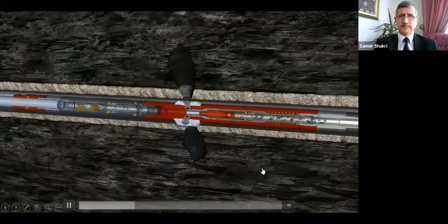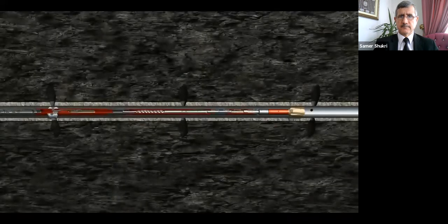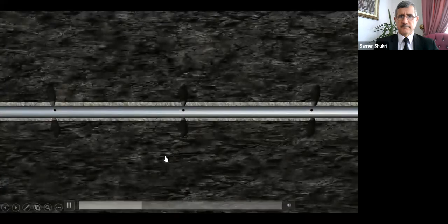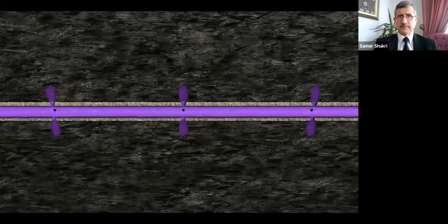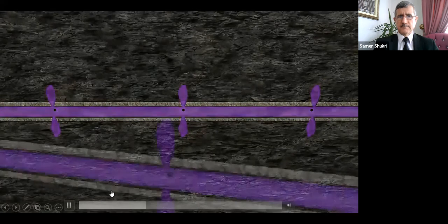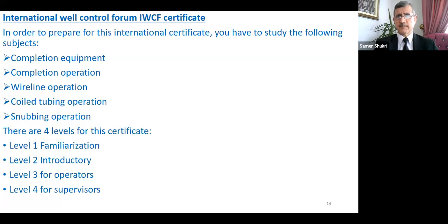Then flow rate is decreased to open the valve and allow flow back to the motor, which can be reactivated to aid in wellbore clean-out of any residual sand material from the perforating operation. After the coiled tubing BHA is removed from the wellbore, proppant-laden frac fluids are pumped from surface to fracture the formation, as pressure builds beyond the compressive stress of the formation. After perforation, we do frac.